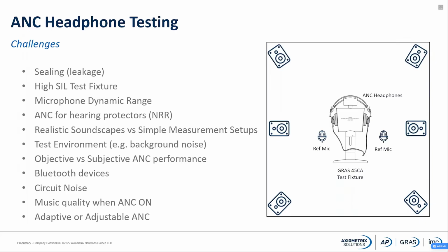And this is the same case when we are having a setup like this. We must be very careful that there's a good sealing between the DUT and the test fixture, so we can ensure that we are measuring the right or the best performance of the headphone when the headphone is properly mounted on the test fixture.